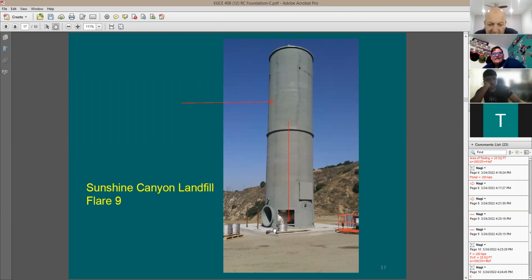So actually this footing supports gravity load and some moment coming from the seismic, which means earthquake force, or wind force. And if the wind changes its direction, it can be designed for a force in this direction, or a force in this direction, or maybe a force coming in this direction, like in the X or Y direction, right? Because the earthquake force can hit in any direction. I cannot really control it.